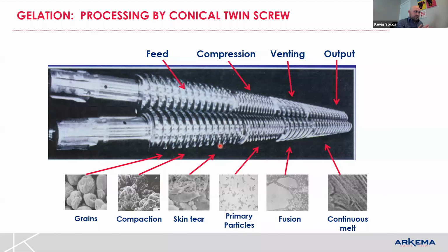The Brabender is a controlled volume. You are supposed to, according to the ASTM standard, put in a controlled volume, not a controlled weight. If you change the amount of filler, amount of TiO2, what kind of process aids you're using, how much PVC is in there, the bulk density will change. When you test, you want to make sure that you're always testing for the same volume. That also helps you mimic it if you're controlling the feed into your twin screw and you're starve feeding it in some way and not flooding it. That's also important because, again, it's a controlled volume that's hitting those screws versus what you might be doing with an actual weight of material.